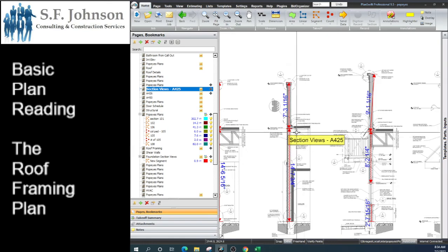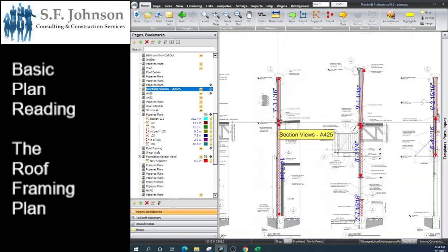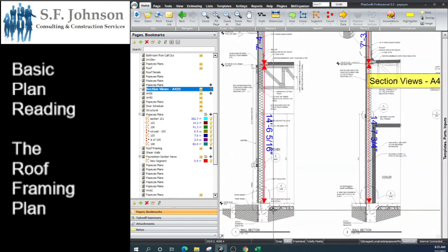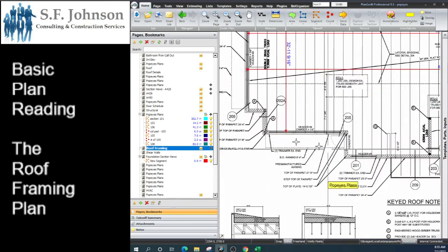So the posts are going to be to the height, to this height. So really depends. You can go 14. And really for the purpose of a cost estimate, you're going to go over. So this is 14, 16 feet, columns or whatever, post 16 feet. You never want to cut yourself too short. So the height of the post would be really the height of these exterior walls. If you needed that information, that's where you could get it. So the posts here, A, B, C, headers, and so on.